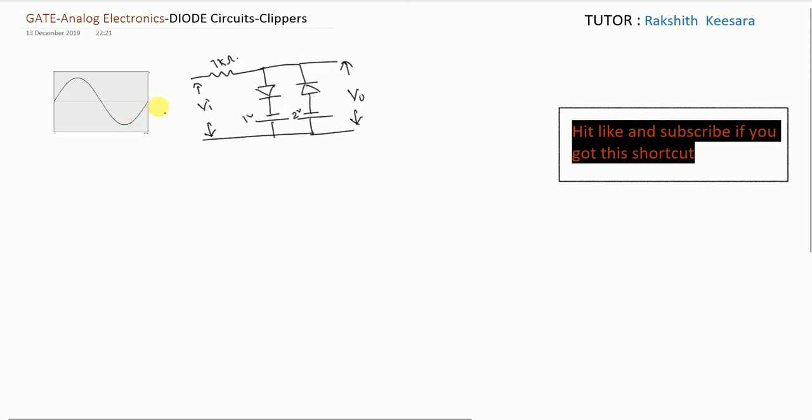Next question, guys, this is the two level circuit. See, what are the reference voltages? Minus 1 volt and minus 2 volt. So I am drawing the minus 1 and minus 2 here. While considering this leg, the output voltage is connected to the positive part of the diode, so the part which is positive is clipped off. Next, while considering this circuit, it is connected to the negative part of the diode, so the part which is negative is clipped off.